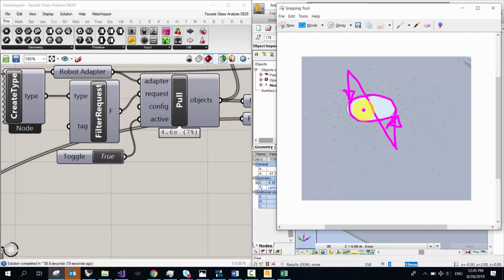So on Monday we discussed, hey listen, if we look at our stress plots, we're getting hogging and sagging moments. And from what we described, a spider connection is supposed to represent something maybe like this in reality, where it physically will act more like a pin at that spider connection. So we should not be able to witness tension on a hogging moment. We want to see this entire panel going straight up, a sagging moment in one direction, right? So that would be an incorrect way of modeling it using the edge supports like we were doing. Everybody okay with that? Engineering-wise, that's incorrect.